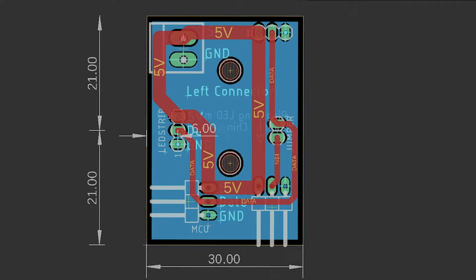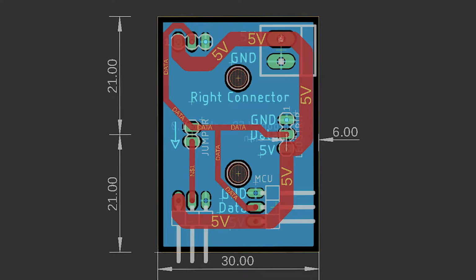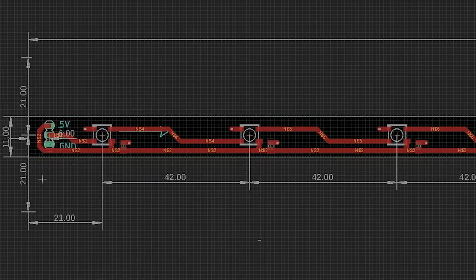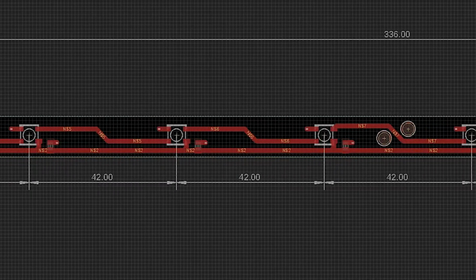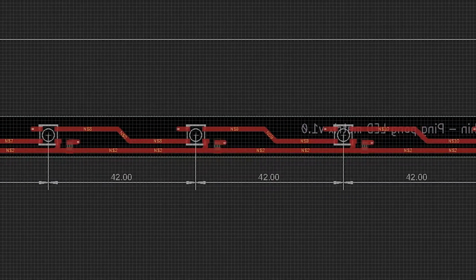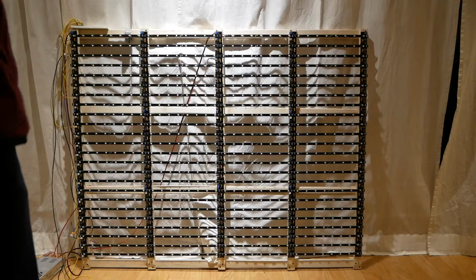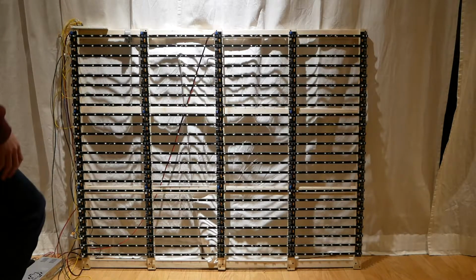I then began work on the design, where each board needed huge traces and ground planes for the amount of current these LEDs consume. Male headers with jumper connectors on the PCBs allow for routing of the data signals to other LED strips for modular control, and the strips were designed symmetrically, so that rotating it allows data to flow left or right with power and ground in the same position. All these features allow many different ways of sending data to the wall.